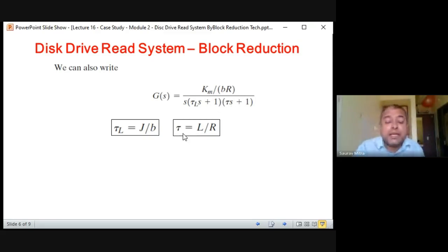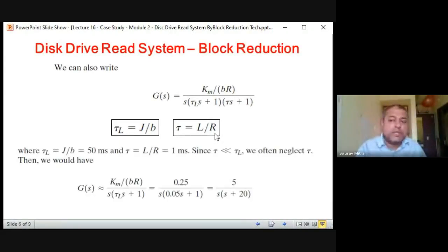What is actually a time constant? Time constant decides the fastness or slowness of the system. Okay, so if the time constant values are very less, that means the system will be acting very fast. So this J, B, L, R actually decide the system fastness or slowness. Fastness and slowness in what? Fastness and slowness in producing the output. That means you are giving a control signal, and how fast that control signal is being digested by the system, and the controlled output is being generated.